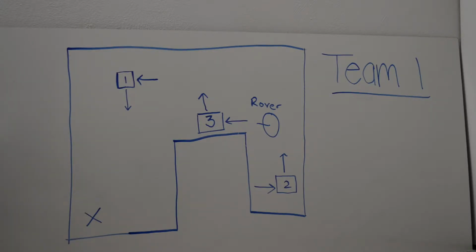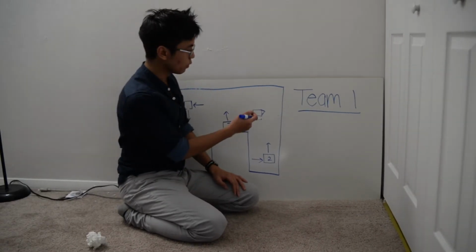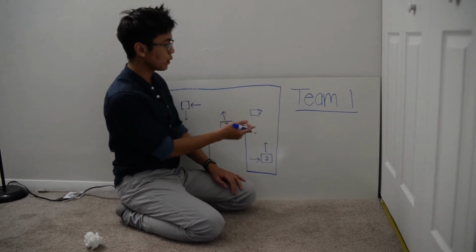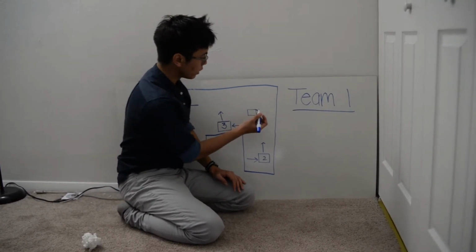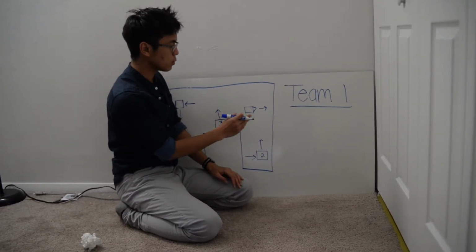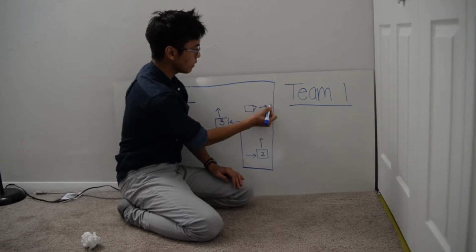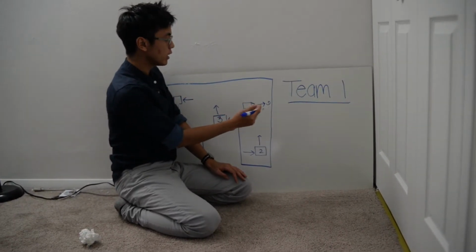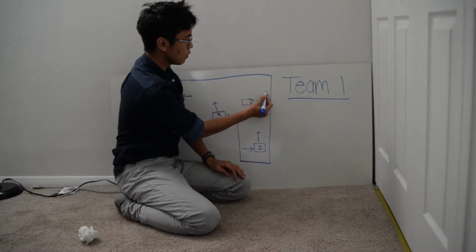The method of discovering the location of the rover was to follow the perimeter of the map, keeping track of the left and right turns taken and the distances traveled between each turn. Along the way, we matched the information of previous movements along with the map data given to us. Once a unique match is found on the map, the position of the rover will have been determined. Now before the rover can start wall following, it first has to find the wall. So to do that, it'll move towards a wall in small steps. Once it finds itself close enough to a wall, it's going to realign itself by rotating, and then it can start wall following.